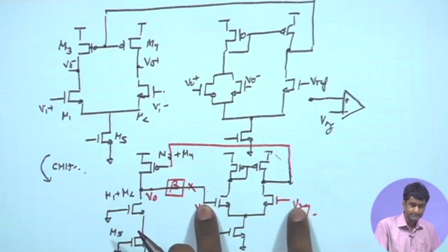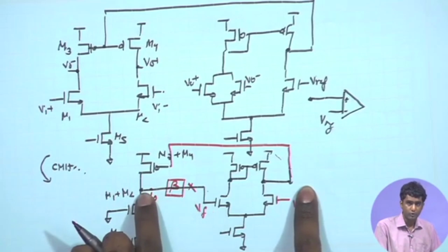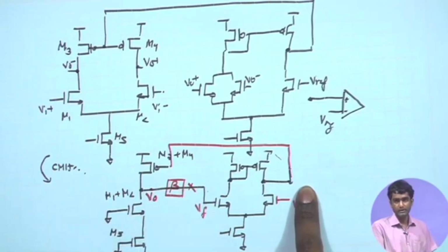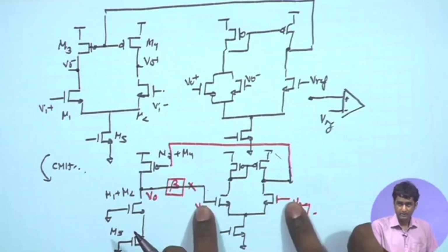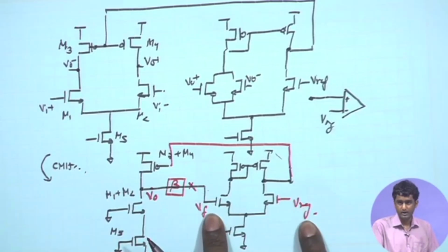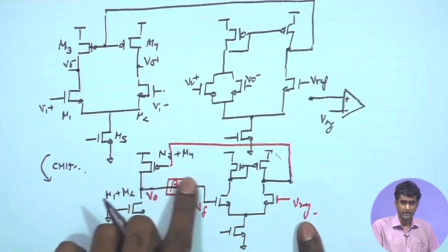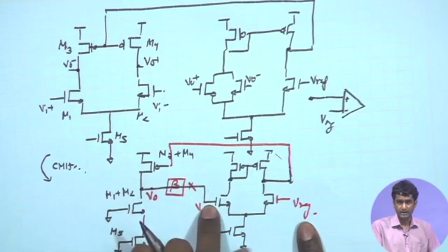So, when you increase this input signal Vref in the positive direction, the VO also goes up, but it is applied to the negative terminal, therefore, it is subtracting from the applied input. So, basically we are having a series connectivity at the input, the feedback voltage is effectively being subtracted from the applied input signal Vref, and at the output whatever VO is produced, we are directly sampling it using the unity beta factor and applying it to the negative terminal.